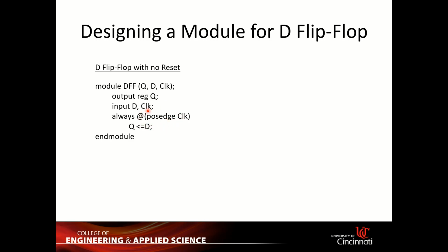You can have a negative edge clock also. When the positive edge clock arrives, what will happen? This statement will be executed. This is non-blocking assignment, the less-or-equal symbol. It is a different thing. This means shift data D to data Q, and endmodule.